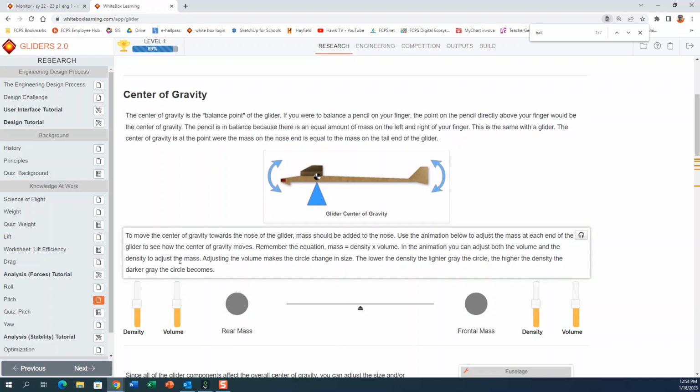We don't want it going down towards the ground. We don't want it going straight up either, because it'll do this thing called stalling. In other words, not enough power for it to go up, and then it kind of flutters to the ground like a leaf falling off a tree. So we want it to naturally fly straight and level, okay? That is pitch, pitching down or pitching up.